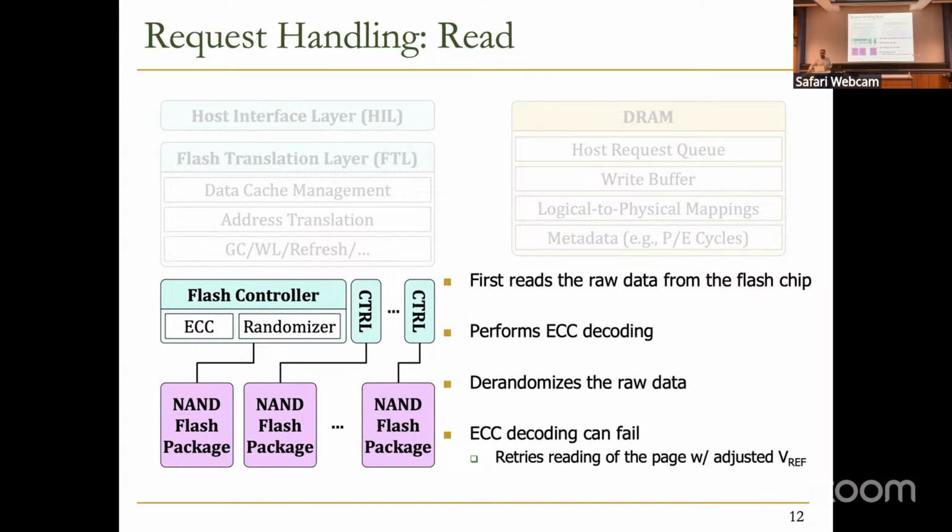No, in DRAM, we don't do that, because DRAM doesn't age in that sense. Yeah, for another reason. Exactly. Because we observe that some rows or some cells can retain charge for a longer time. So we have a refresh retention time profile, which we could use for a variable refresh technique. But here also, yeah, you can adjust the refresh period based on the program erase cycles, for example. Yeah, good question.